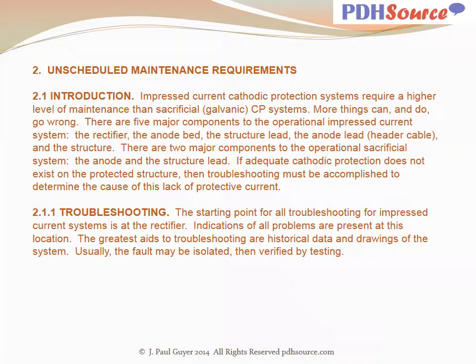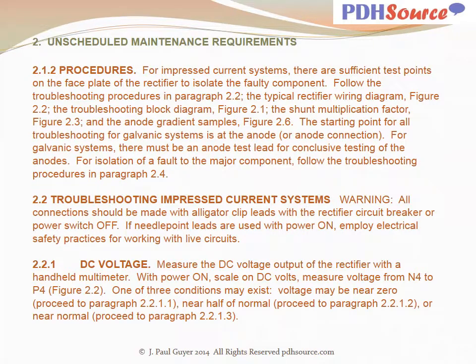The starting point for all troubleshooting for impressed current systems is at the rectifier. Indications of all problems are present at this location. The greatest aids to troubleshooting are historical data and drawings of the system. Usually the fault may be isolated, then verified by testing.